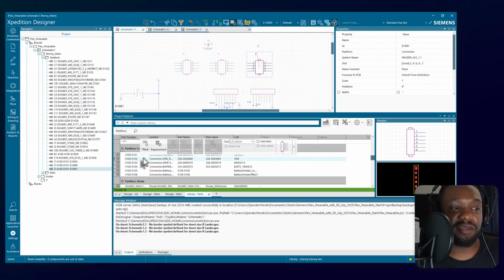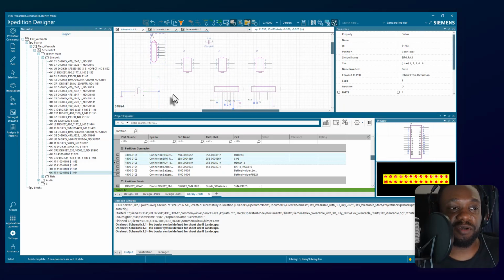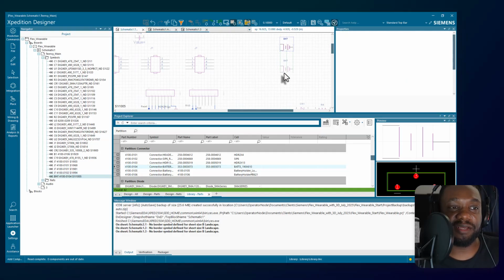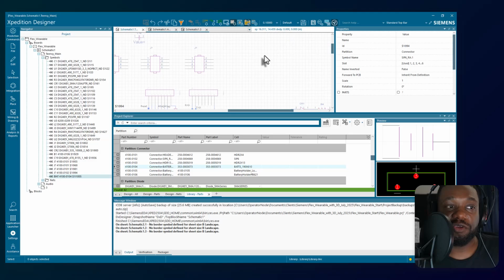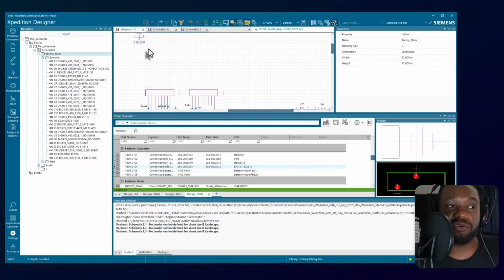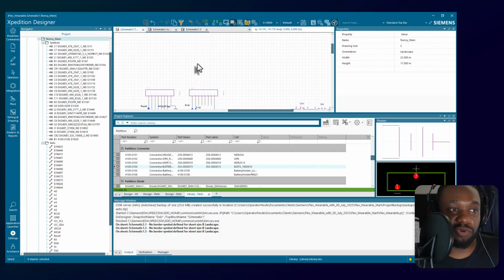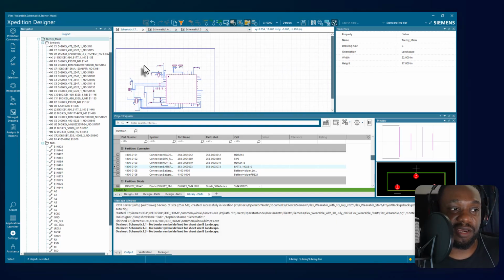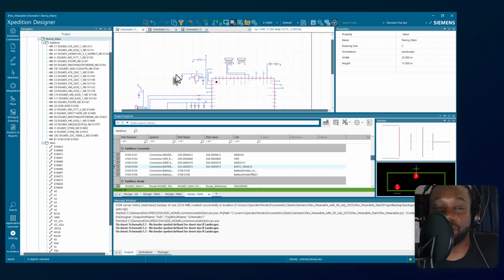Very cool. So if I click on here, I double click, no problem. Let's see if I can drag it onto the, see, I can't drag it on the schematic. That's okay. I do like being able to double click on things and then click and place them. So that's pretty good. You can also do your standard Control Z to undo things. Click on a component and delete that. You can do a Control Alt to select all components and they get pulled up in the design. So I like that as well. Navigation, you can scroll up and down to zoom in and out, pretty standard, and I like that as well.